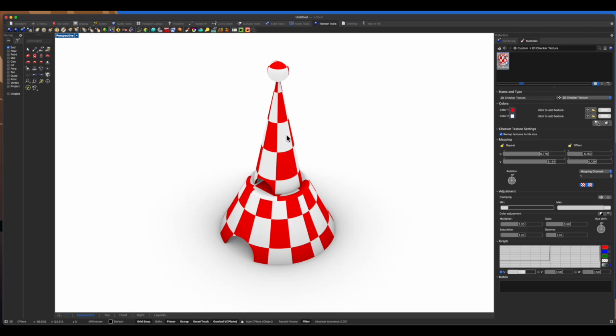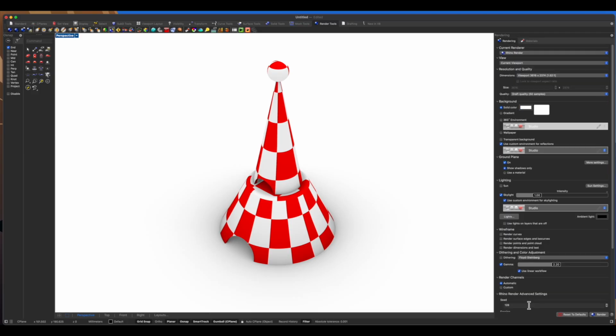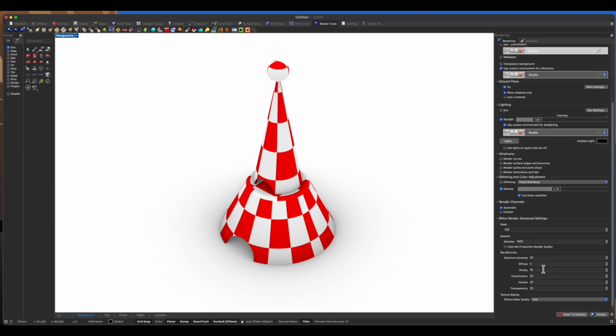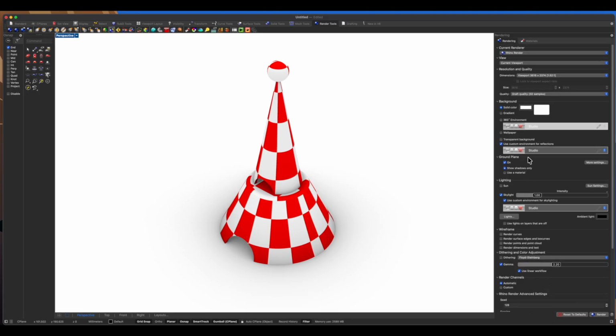Now you can save this as a file. So for that you need to do the rendering, go to the rendering. Now there are a few things which need to be taken care of. If you are going with the resolution, suppose you need to make an image, this is a very important setup initially. So here I'm making a 4K resolution. Draft quality I will keep low quality.